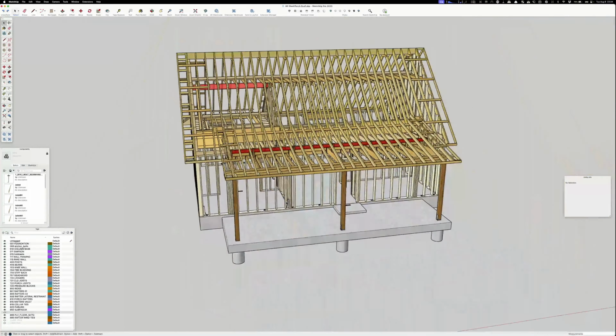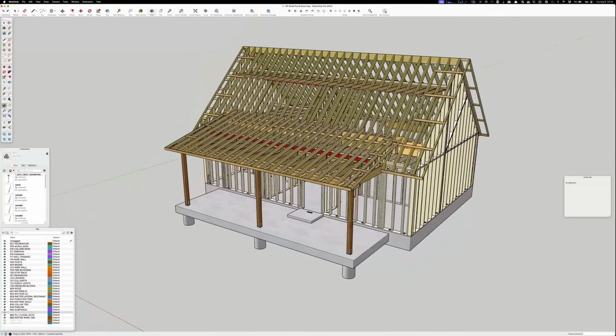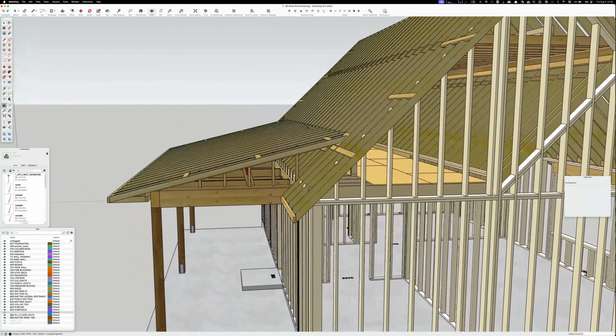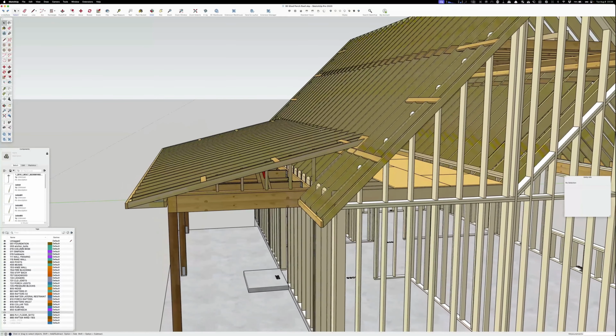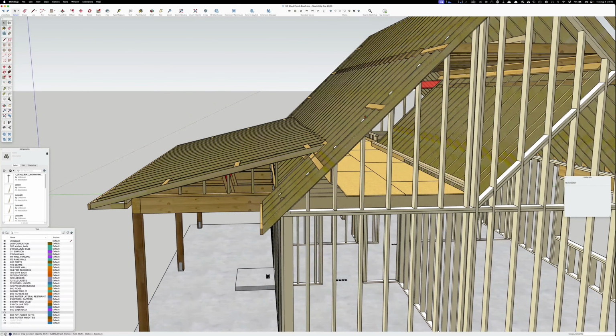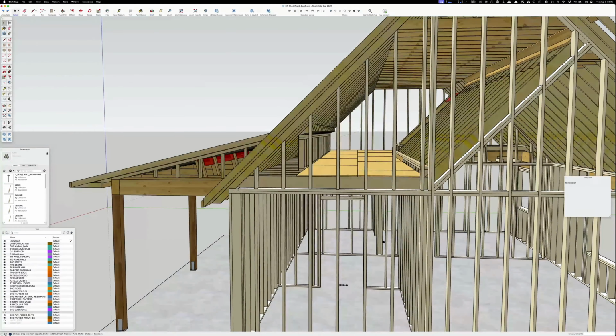So this was pretty much what I wanted to show. I'll just go over the steps as a framer. The first thing you would do is make these rafters of the main roof straight, as in not sagging or being bowed. So that might require a temporary purlin all the way across here. And you don't even need to brace it, really.